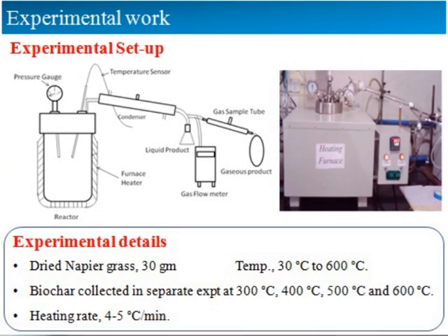So if I do a pyrolysis of biomass, I get gas which I use for burning for cooking purposes. The liquid which I get is mostly carboxylic acids, acetic and formic acid, and I can use that liquid for recovery of chemicals. And the char which I get, I can grind and remix with the soil to improve the productivity of the soil. And indeed this is possible, and I'll show you some typical examples of this. This is a typical experimental setup, a reactor.